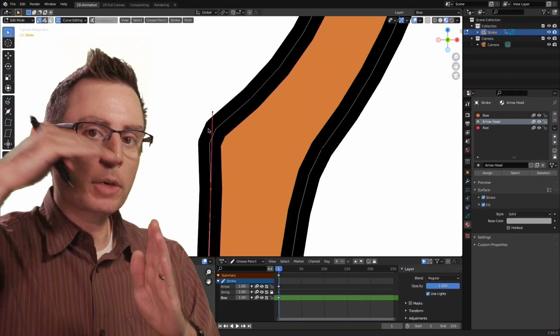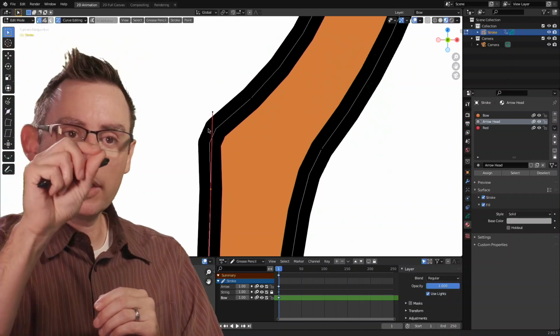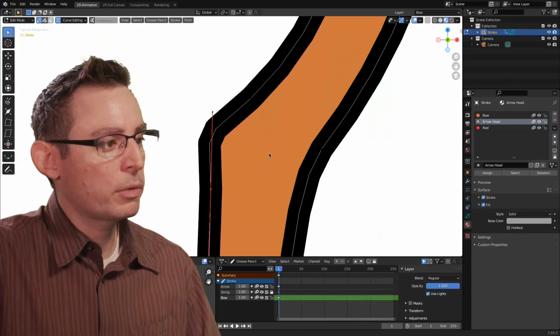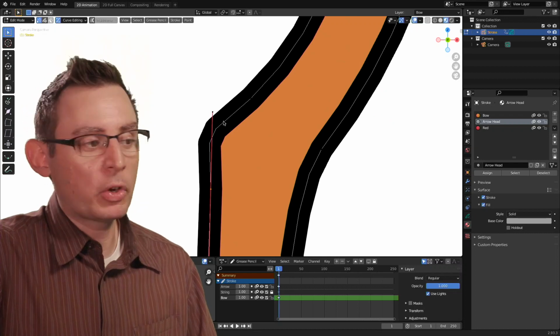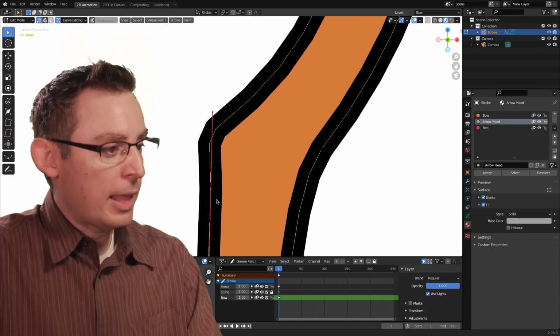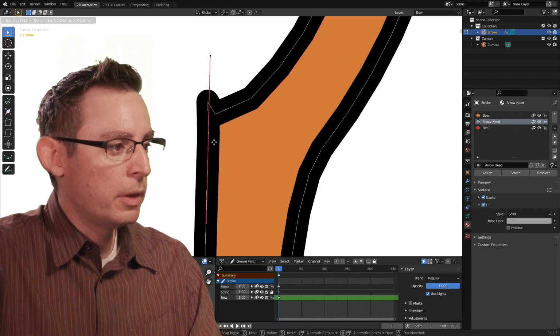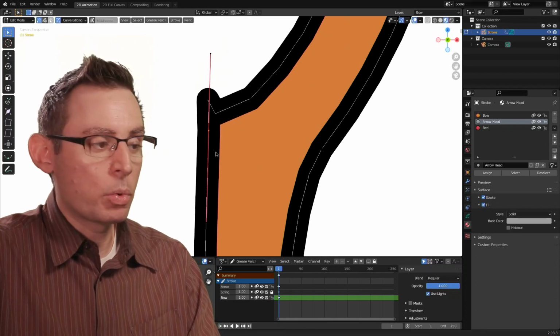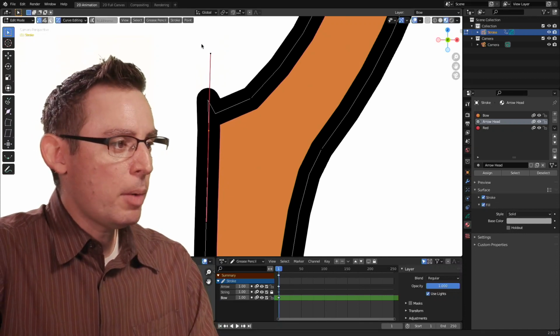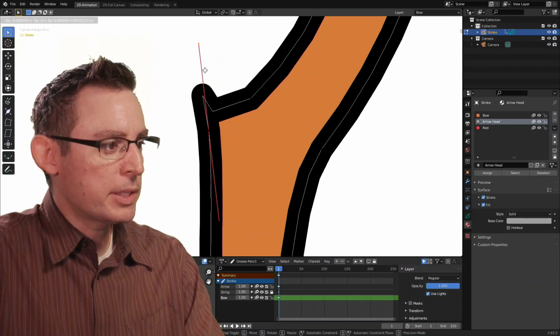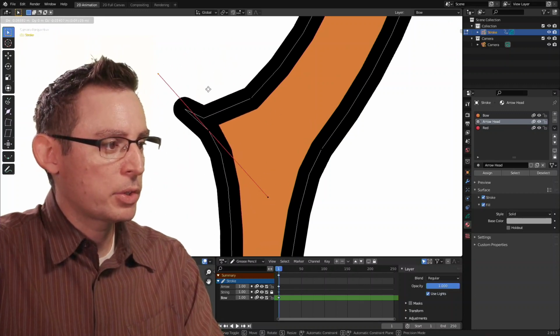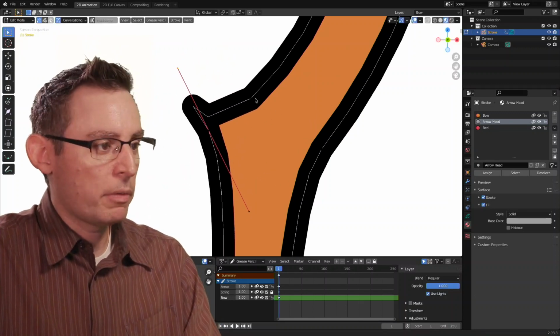When you're dealing with sharp corners and trying to make a quick transition between two different curves, you want to define the location of the transition with the corner point itself. Now, the problem that we're running into are these tangent handles, right? These tangent handles are turning into big problems. We're going to resolve that here in a second.